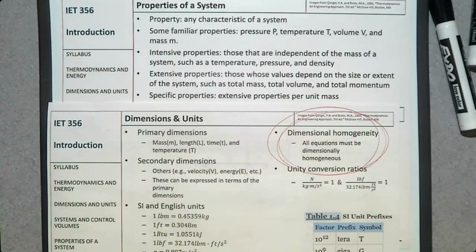Those that were extensive properties and became intensive properties by dividing by mass are called specific properties. So when we use a governing equation in general in thermodynamics, we use only intensive properties and specific properties. And if you know the actual numbers, you can simply multiply by mass at the end of the calculation.